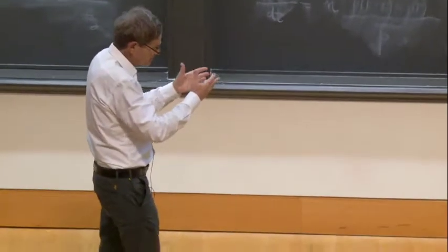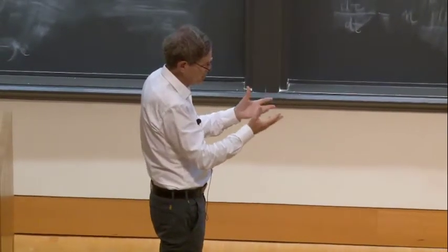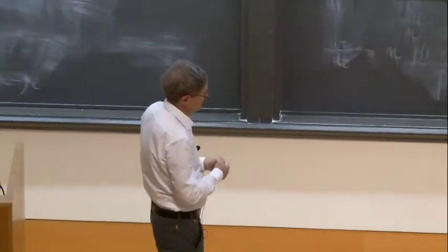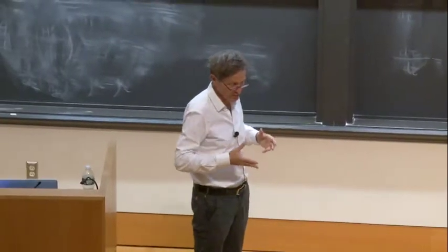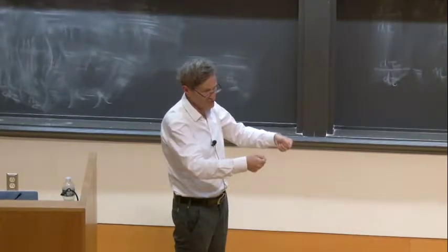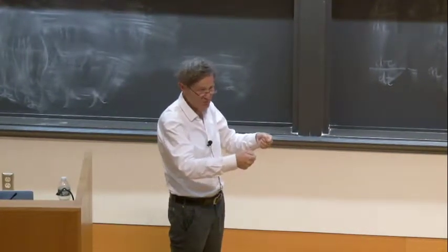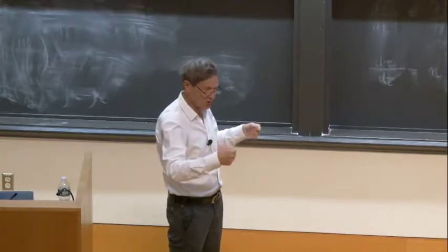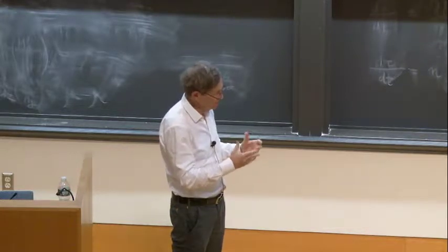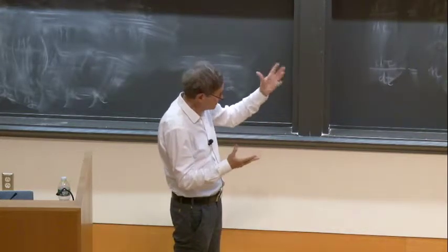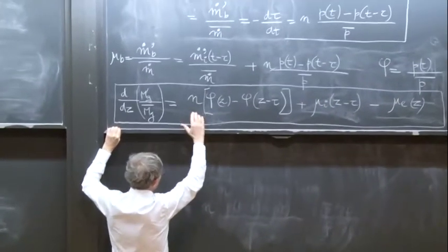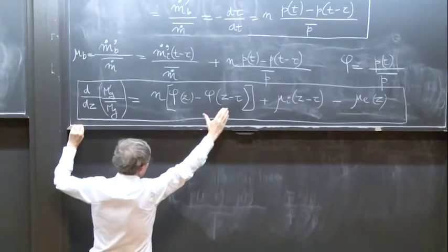It's a rocket engine, but the same ideas can be utilized for other systems, systems which look somewhat like a rocket. And usually you have a combustor, you have reactants getting into the combustor. There is a certain residence time. If the residence time is too short, it's not good. If it's too long, it's not good. And then you have the problem of vaporization and so on. And all this is more or less represented, but of course, somewhat empirically, through this interaction index and through this time lag.